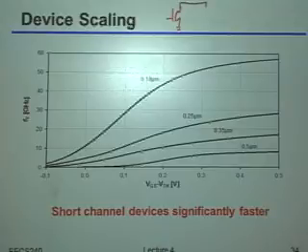So let's just pretend I have a simple common source amplifier, and I've got some explicit fixed load capacitance I have to drive. Now, as you decrease that V star, what are you doing from a sizing standpoint to the transistor? Is the transistor getting bigger or smaller? Yeah, it's getting bigger, right? If the transistor is getting bigger, what does that mean about its parasitics? In particular, let's think about just the drain to body parasitic. As you decrease the V star, is that parasitic getting bigger or smaller? Yeah, it's also getting bigger, right?